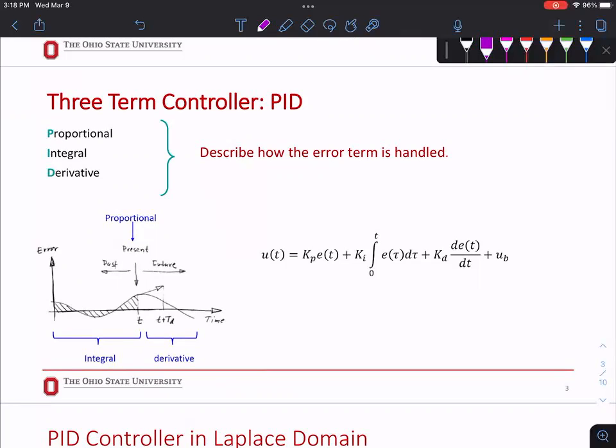Now, PID controller, we have proportional, integral, and derivative. 3 different terms. They have coefficients, and we represent those names with the coefficients. So KP, KI, KD. We reserve P, I, and D for the PID controller, so try to be consistent. Don't say KR, because I wouldn't know what KR is. But I always know when I see KP it is going to be something that relates to position. Do you remember, when we were defining the static error constants, we had KP, KV and KA. KP was position error. This is the same thing.